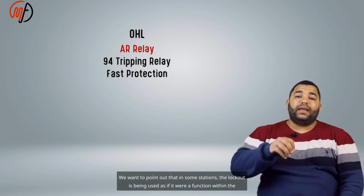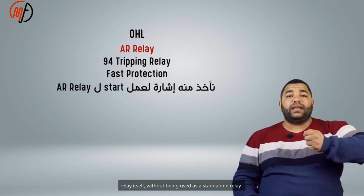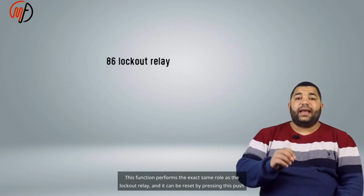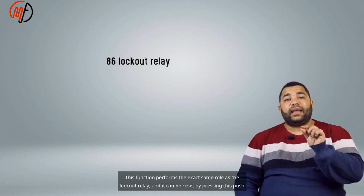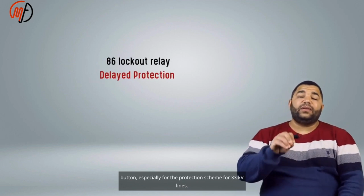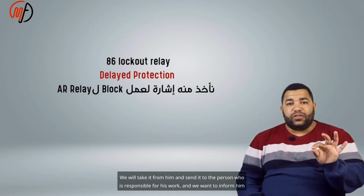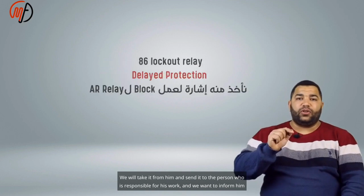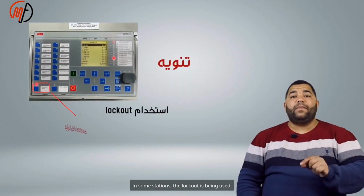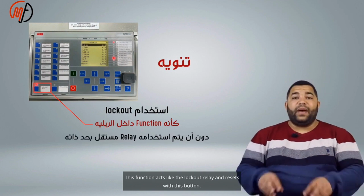We want to point out that in some stations, the lockout is used as a function within the relay itself without being used as a standalone relay. This function performs the exact same role as the lockout relay, and it can be reset by pressing this push button, especially for the protection scheme for 33 kV lines.